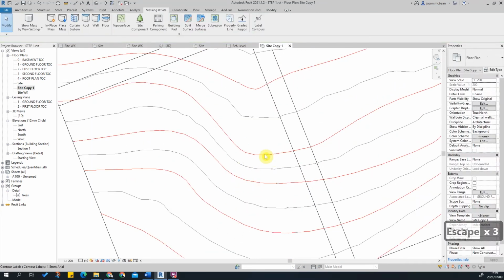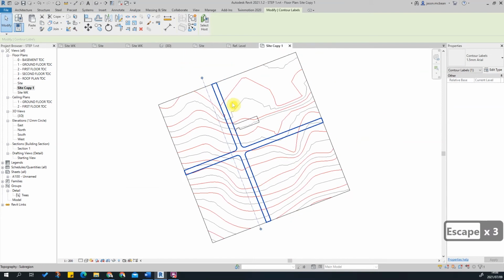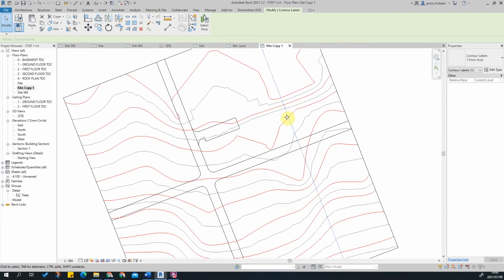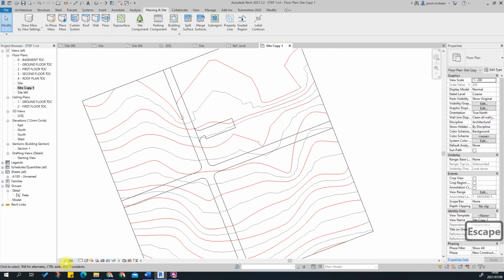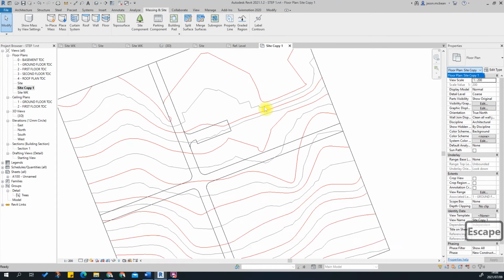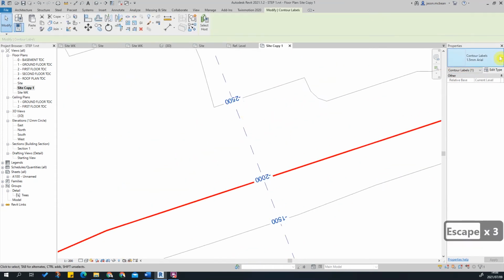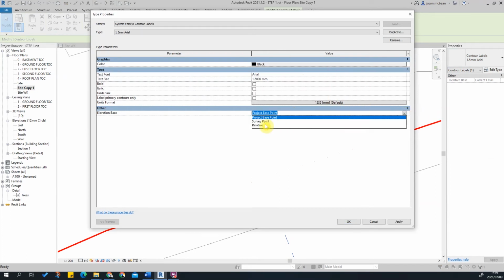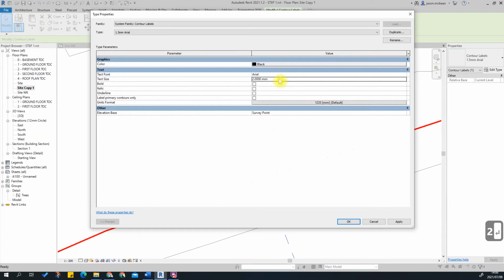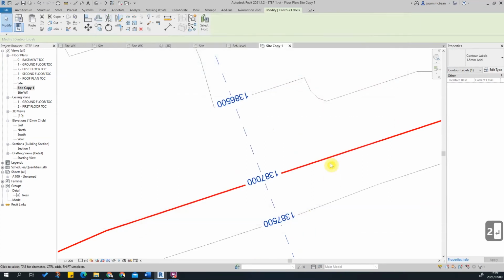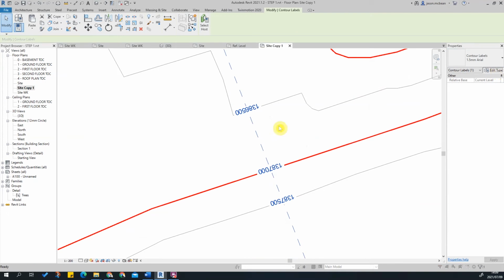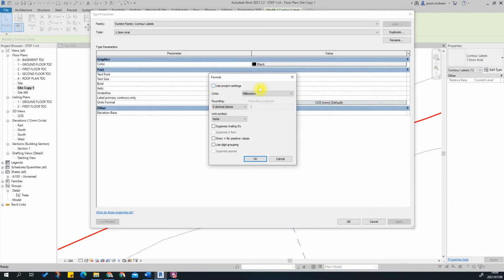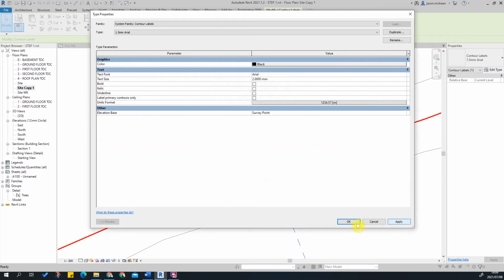With those on, I'm just going to take some down on that side and use the copy tool and go on that side. And then I'm also going to change the scale 1 to 200. That's fine. Okay, let me just make sure that this is working correctly. That must use your survey point. Just remember that survey point. I'm going to change these all to 2 as well. Press apply. Press OK. Okay, and we just need to fine tune some of those values. So units, meters, 2 decimal places. Press OK. Press apply. Press OK.